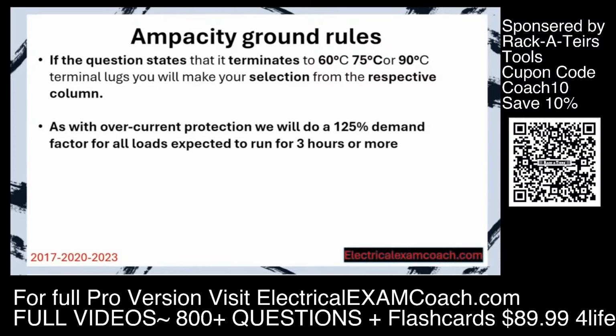And as with overcurrent protection, we're going to do a 125% demand factor for all loads that are expected to run for 3 or more hours. Remember our continuous load rule? That carries over into wire sizing as well.